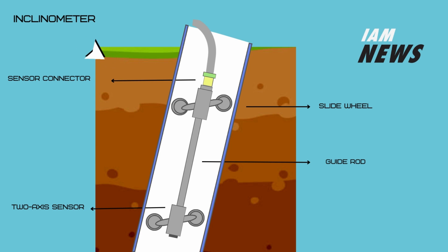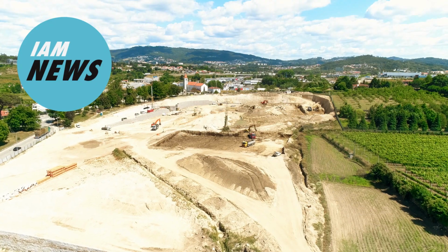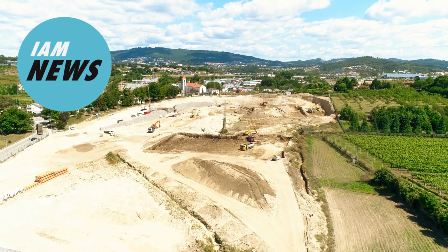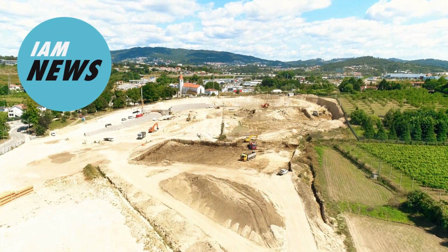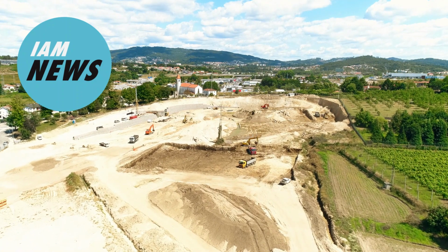Inclinometers, which measure the inclination or tilt of a section of ground or structure, also follow the principle of a sensor and a reference point to provide engineers with vital information on the magnitude and direction of an incline. While satellite data allows whole infrastructure networks to be monitored and potential problem areas pinpointed, geotechnical instruments are the tools to provide the detailed, below-ground information needed to effectively manage, maintain, and solve those problem sites altogether.